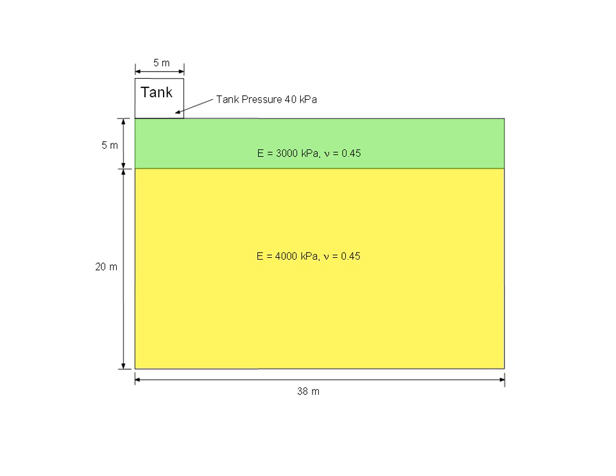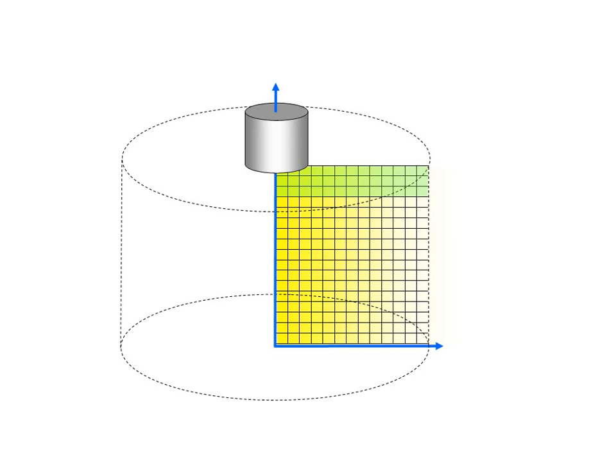Since the profile is symmetrical around the vertical center line of the tank, the problem will only include half of the tank and will conduct an axisymmetric analysis. An axisymmetric formulation considers the stresses in the xy plane as well as the circumferential stresses, and the profile you create is rotated around the axis of symmetry.